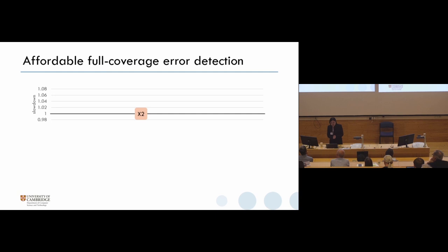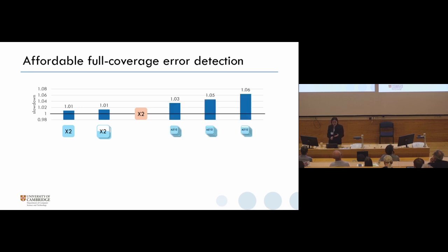First, I will show the results on our full coverage error detection. Compared to a baseline where there's only a main core running the workload, adding the big cores for checking only adds about 1% slowdown. Little cores add a bit more slowdown, and naturally lower frequency shows more slowdown. But on the energy side, that's where we get more affordable. With an identical core, there's about 87% energy overhead. This is high, and comparable to a dual core lockstep system.